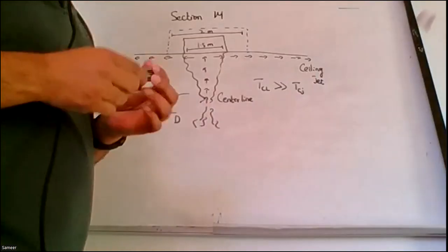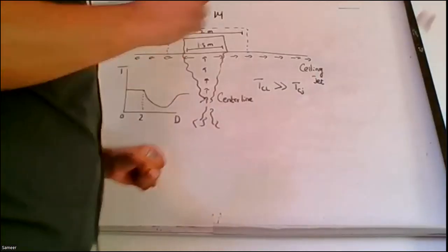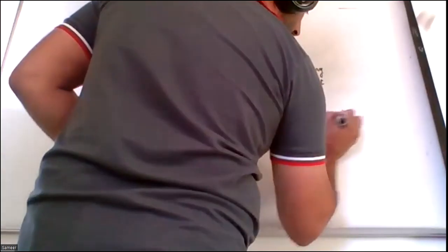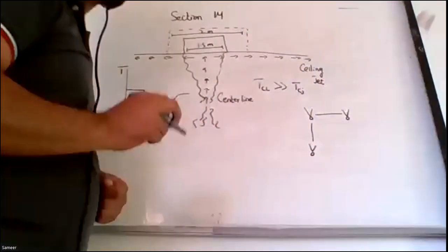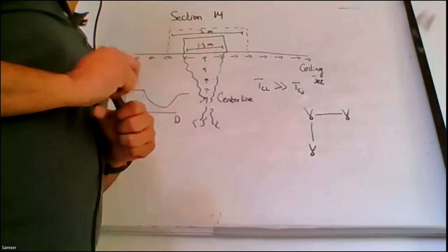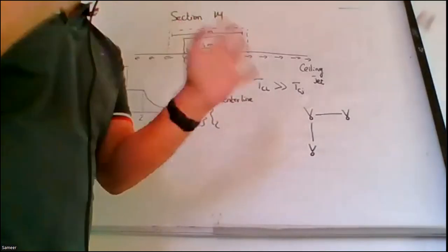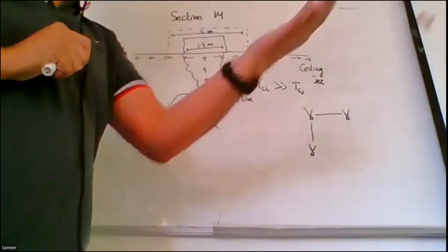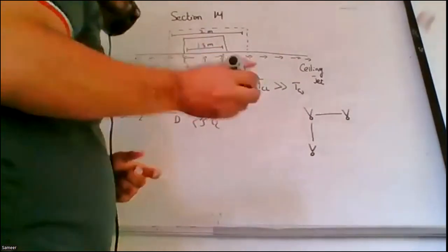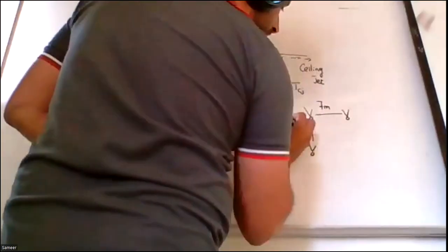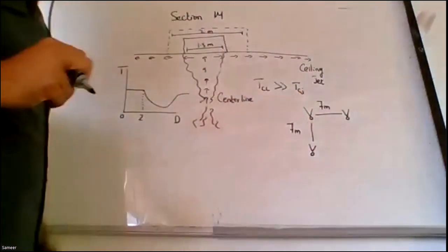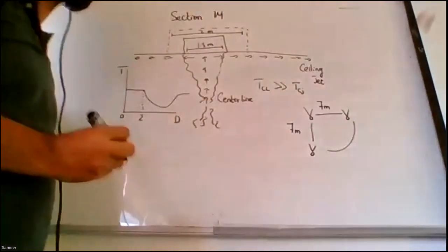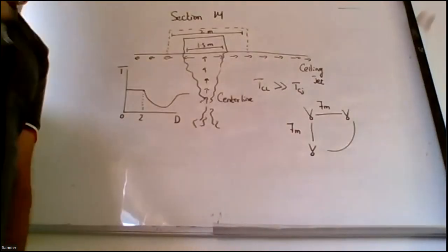9 meters for smoke detectors. Heat detectors. NFPA 72 says that the heat detector distance is based on the manufacturer's instruction. It does not specify any distances. The UAE Life Safety Code says that whenever you use a heat detector, it should be 7 meters apart. Some manufacturers make it 5 meters apart. 7 meters apart means the area of detection will be 49 square meters, right?